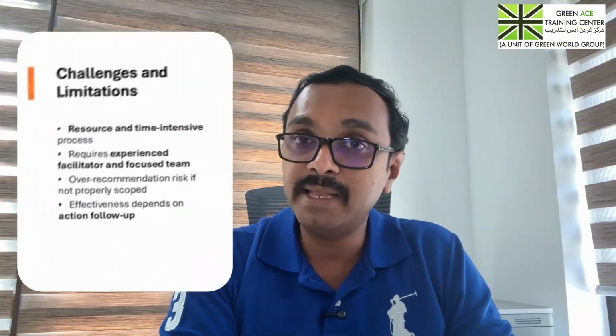And of course, coming back to the topic, for conducting a particular HAZOP study, we require a lot of competent manpower from various streams within that particular process industry. And as I said earlier, it requires an experienced facilitator and a focused and knowledgeable team. If the scope is not clearly defined, then there are risks of sometimes over-recommended actions that are truly not necessary. So that also needs to be considered.